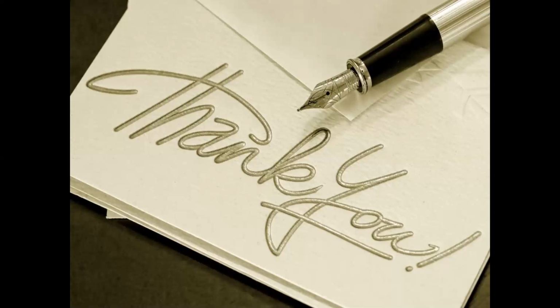This is what they inferred, and RILEM finally concluded that you cannot take it as a clear-cut number where you can use these data for doing the analysis in terms of repair and rehabilitation. So I'll summarize it. This is a very widely used and very long standing test. From 1940 it has been used, but it has got a few limitations and a few advantages. The advantage is that you will be able to know the cover concrete quality, the surface concrete quality. So it is only a qualitative test, it is not a quantitative test.